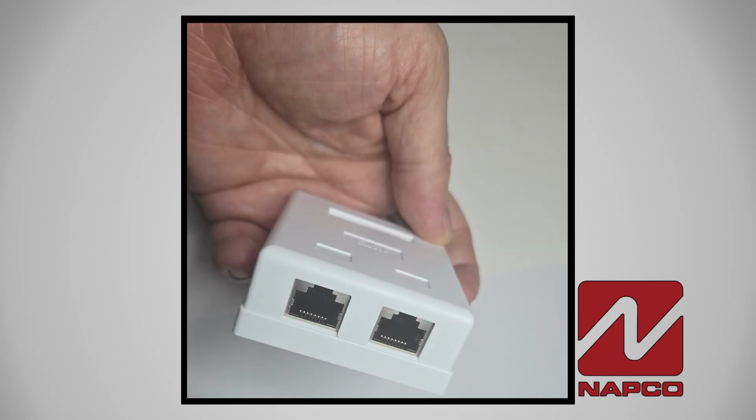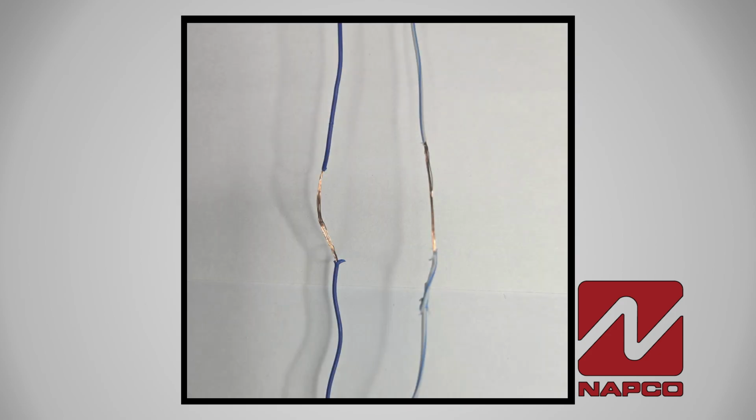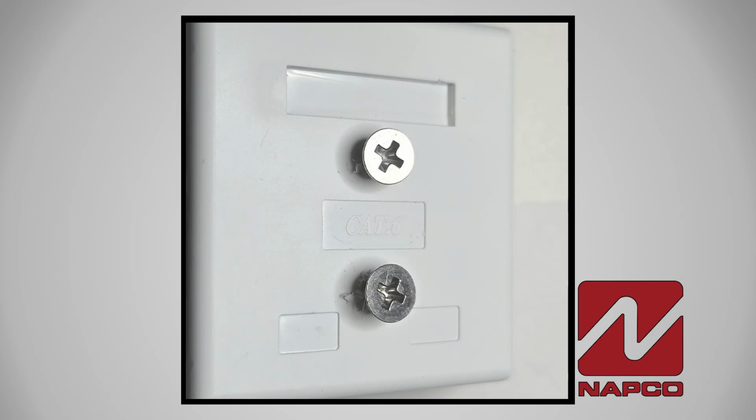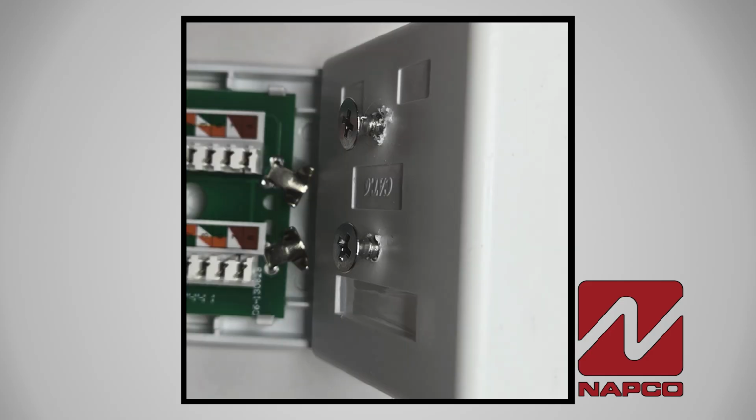connection though. I promised I'd show you how to build that simple tap that I used earlier in the video, so here it is. First, you want to get an RJ45 connection block with 2 ports. Next, you get 2 lengths of wire you can work with and strip back a section in the middle on each. Now, grab yourself a couple of self-tapping screws and screw them into the lid. You don't want them to go all the way down, you want enough to stick out so your butt set